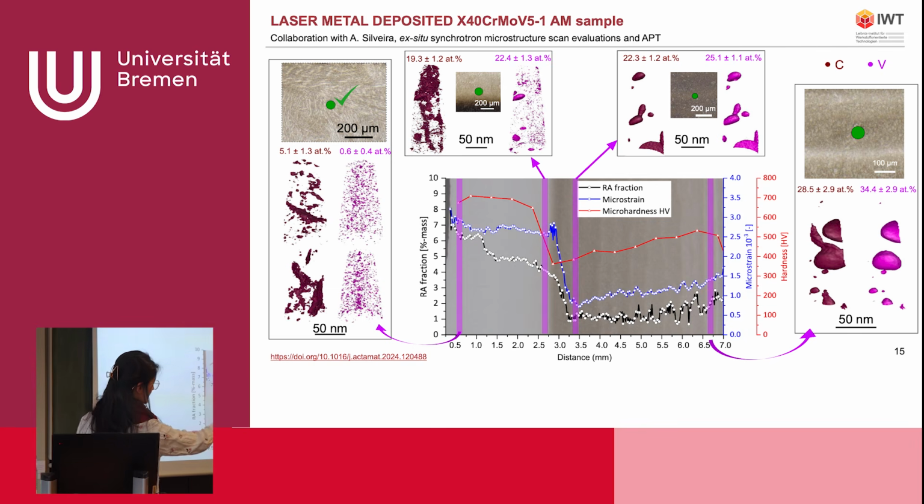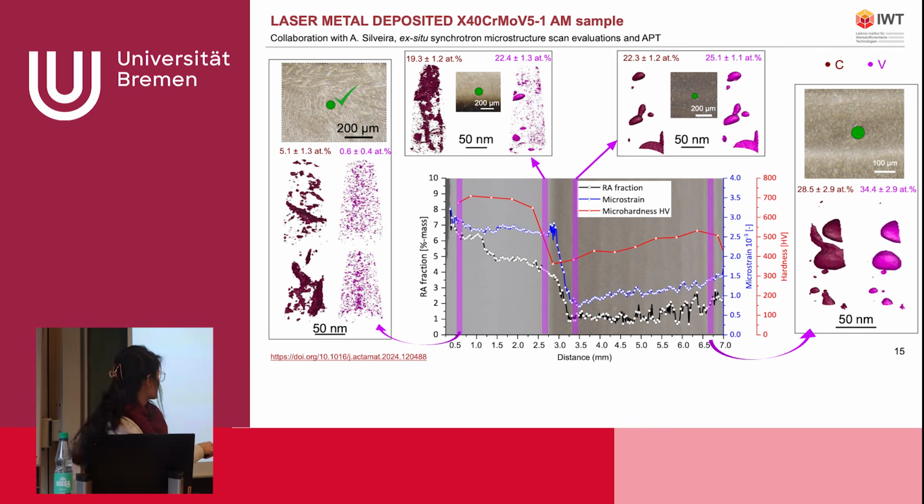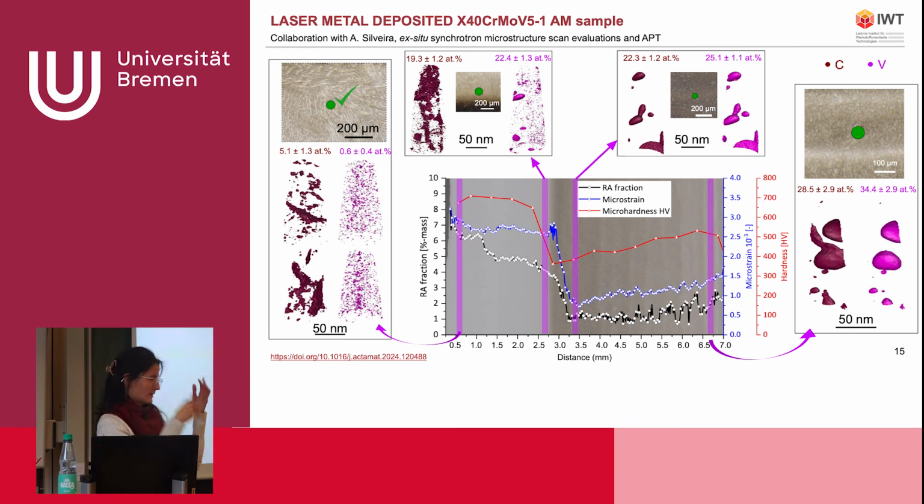This was the first layer, and this one was the last one. This region here was directly quenched. When the layers here were deposited, they were directly in contact with air, but they were not heated up again and again like it was the case for these ones.